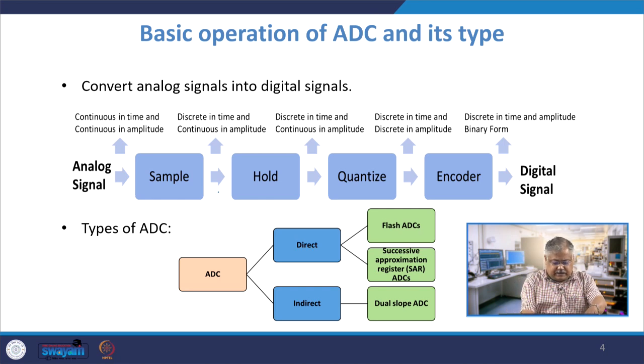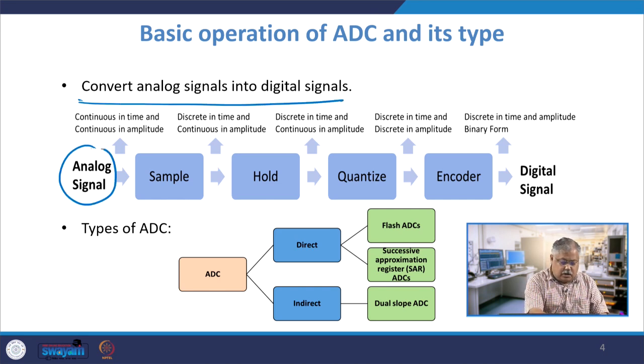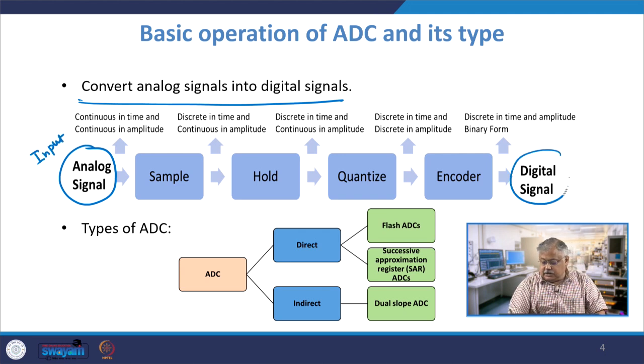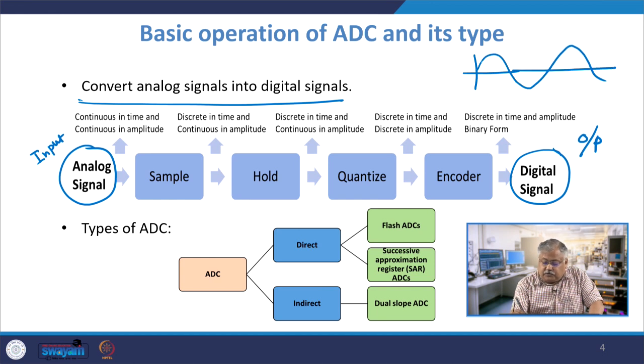this is how you convert an analog signal into a basic digital signal, right. I have an analog signal here, which is my input, and my final aim is to get a digital signal, which is my output. So, analog is something like this, right. You first need to do what is known as sampling and holding the signal. Sampling means you are sampling the signal in this manner, right, and then holding the value so that the exact value can be replicated in this manner.